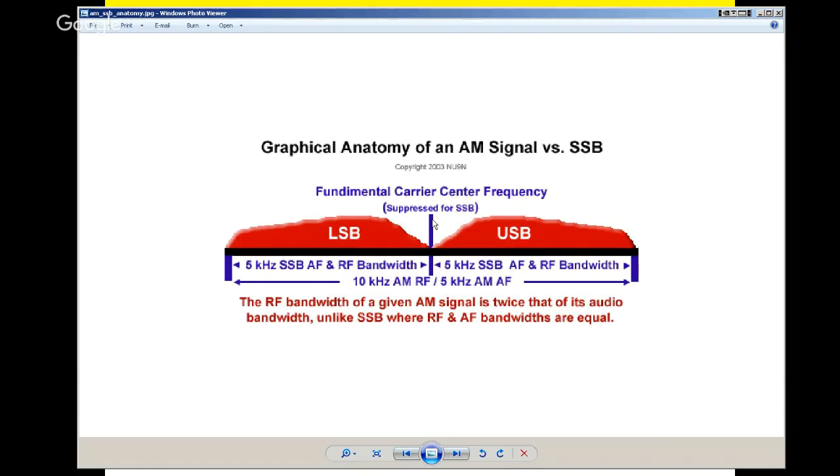Their bandwidth is going outside the normal bandwidth of the pass band of the signal. I don't want to get too technical here because it's not really relevant to passing the test, but I want to explain it in lay terms the best I can. The lower sideband of channel 11 is bleeding over onto the upper portion of channel 10, and it's messing up your receivability.